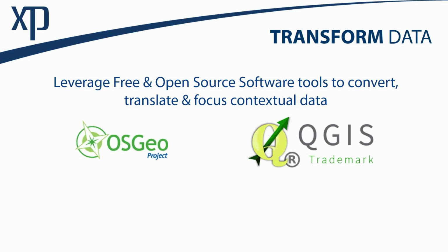We also need to look at the metadata, so the information about that. For example, a lot of data is in GeoTIFF format in a metric UTM coordinate system. Coming from the US, I use Imperial for all my design projects. So XPSTORM is unable to perform those coordinate transformations on the fly between UTM and the state plane coordinate systems. So we want to translate and focus that data with some tools.